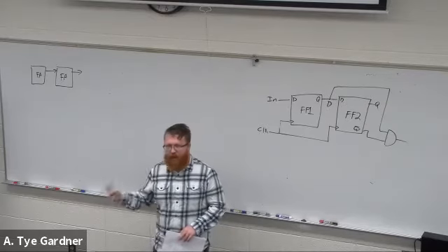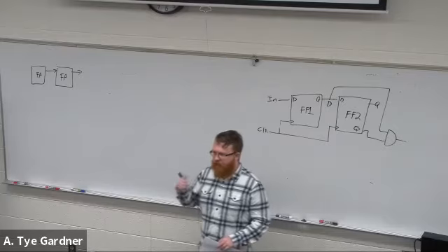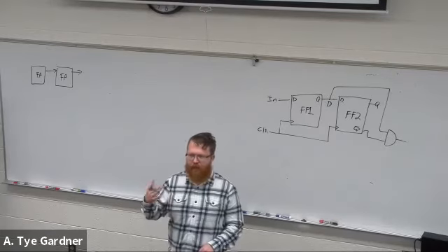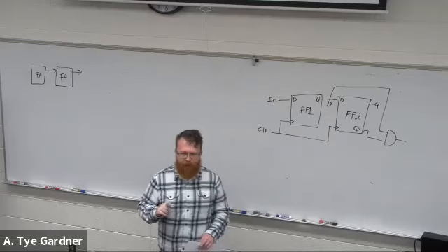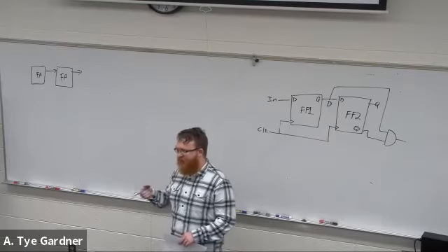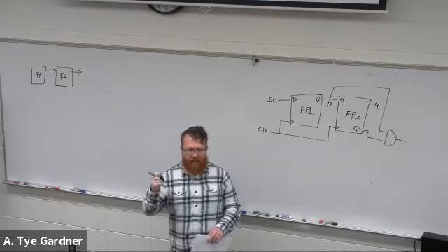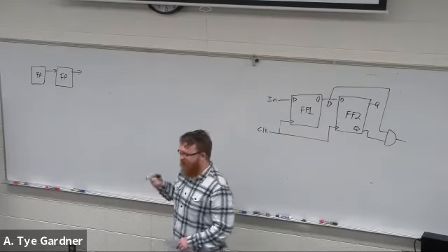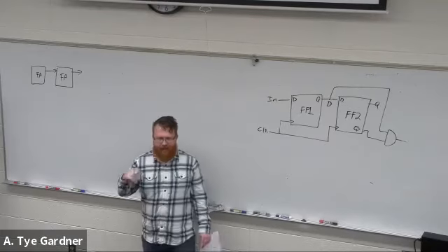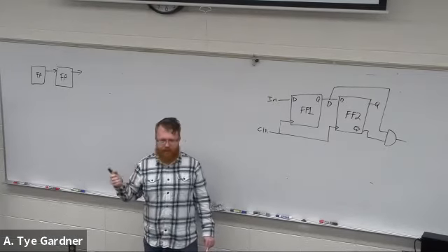It knows for you. However, why I think this is cool and useful is it introduces you to some of the more advanced design concepts that will help you develop future algorithms. So if you end up trying to build DSP components, understanding the CLA, carry look ahead adder, is like the first step, because this is one of the easiest to grasp complex systems. Next time, I believe, we'll talk about multipliers, and those start getting really cool.